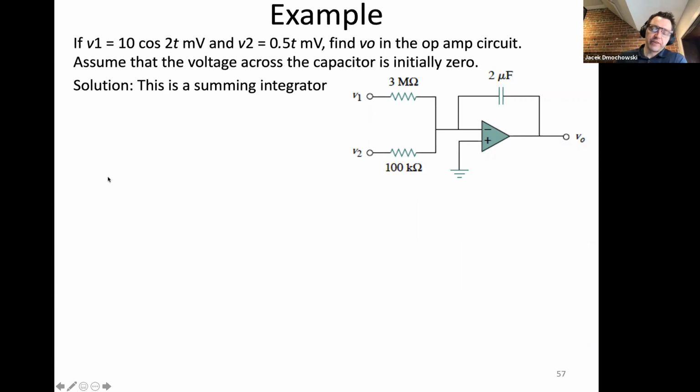It will just saturate. So if you ask it to produce higher than what it can, like for a power supply of, let's say, plus and minus 5 volts, the highest voltage that it can produce relative to ground is 10 volts, for example. So it will just always saturate at 10, no matter what the correct answer should be. It doesn't break. It just clips. So I don't know if you've ever looked at a music waveform, like an audio waveform, where the signal is clipped. So like it's hitting the ceiling. That's basically what the op amp would be doing.